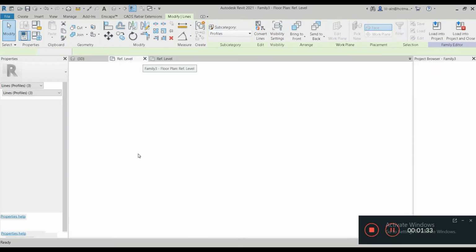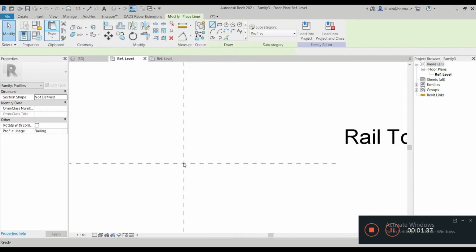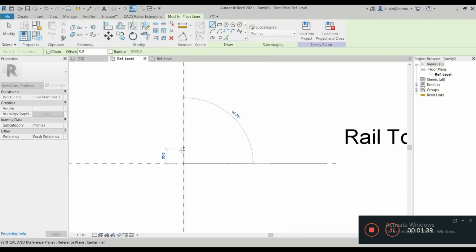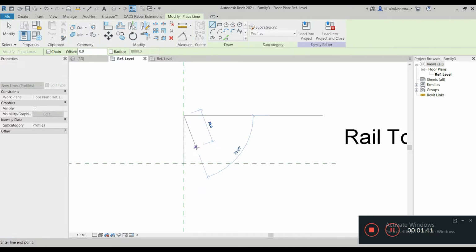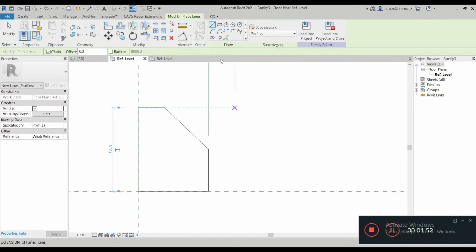And so once we're done with that, now we have made that family of the footpath, the sidewalk, and we've saved it. Now it's the curb that we'd have to make. We save it, and then at the top right you could see load into project. So these are the two families. So this is the rail method, okay? Creating roads and curbs by the rail method.